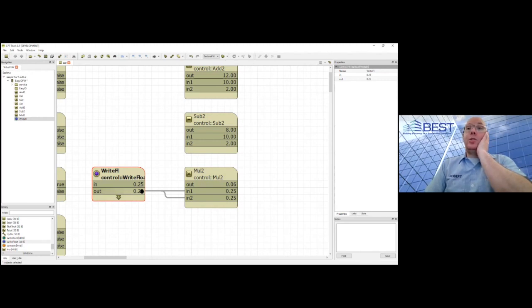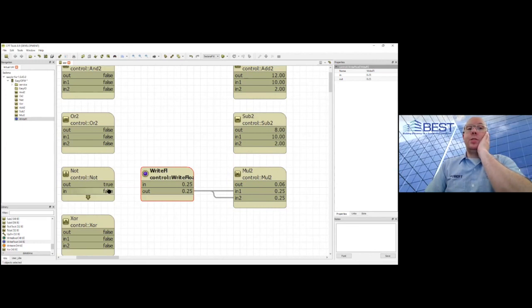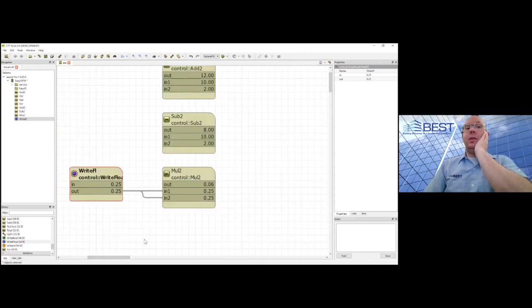Now, what I did just there was why we call this a wire sheet. I've wired these two blocks together. To do that, grab onto the number of the output, or if you're dealing with Boolean values where it says false, do be careful to grab an out value, not an in value. That one will mess you up all the time.